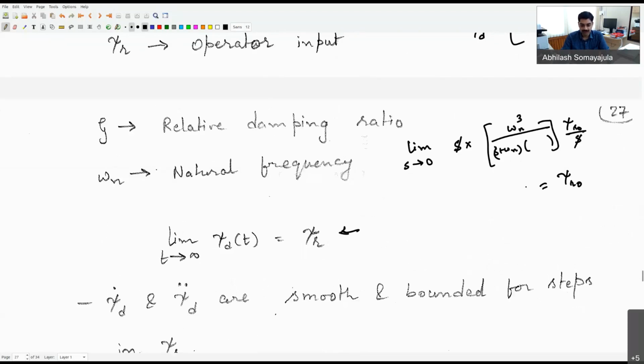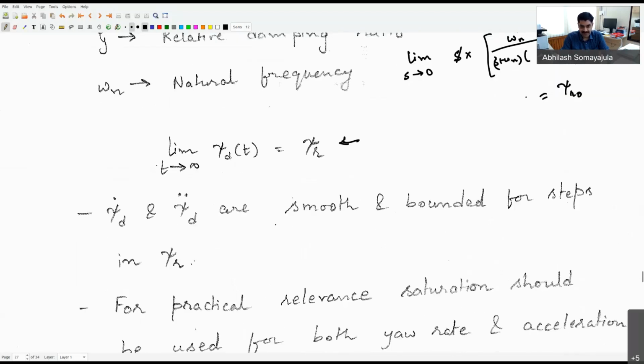All right. So notice that in this approach, when we compute our psi d, psi dot and psi double dot are also smooth, and that is why we went for a third order filter, so that even psi double dot is smooth enough. If we only went for a second order filter, then we might have seen a non-differentiability in psi dot or psi double dot possibly happening.